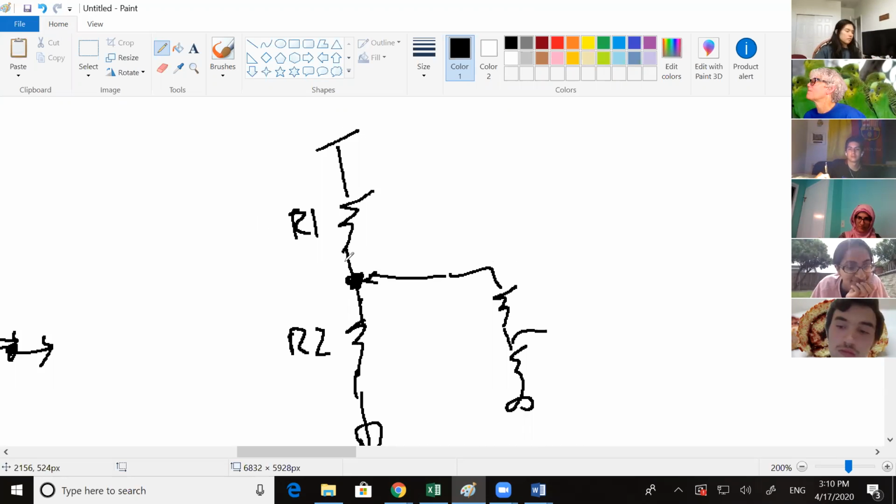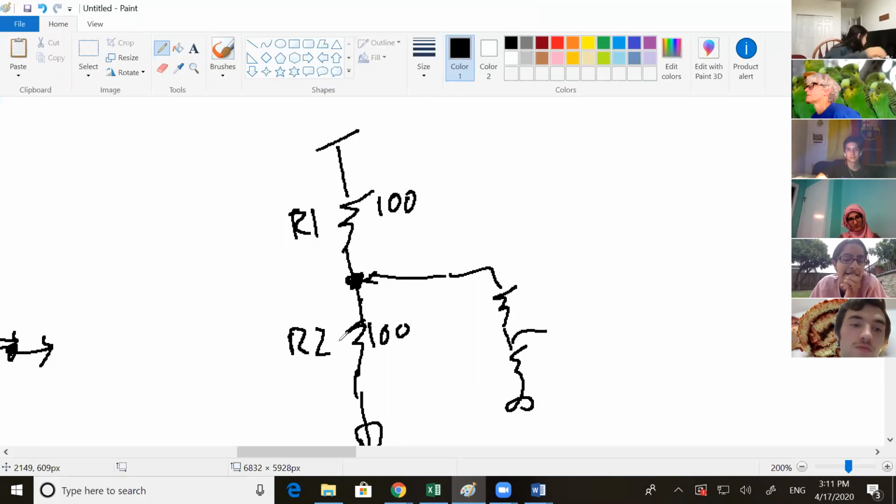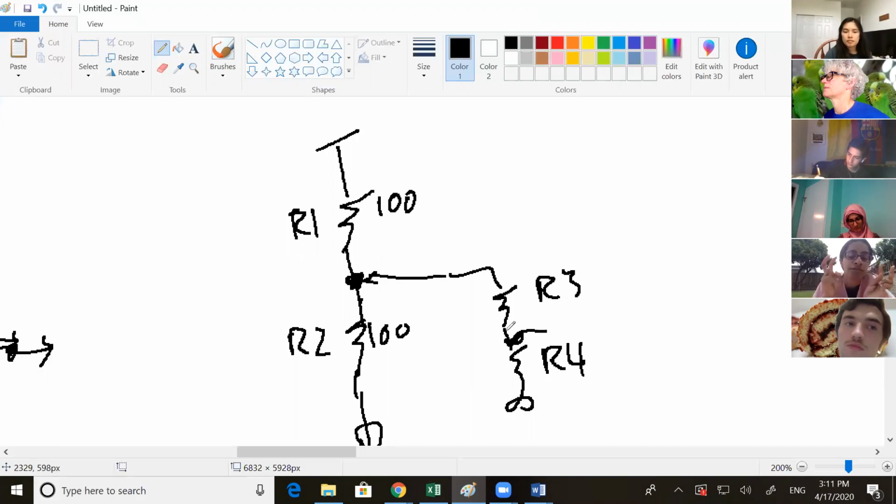And so let's see, team. What answers did you all figure out for this one? It might have been a better resistor, like smaller tolerance and all that, but that won't help this specific problem. We found that with the bigger resistor, you got the values you wanted. So I just said that was the fix. Okay. So make these big, right?